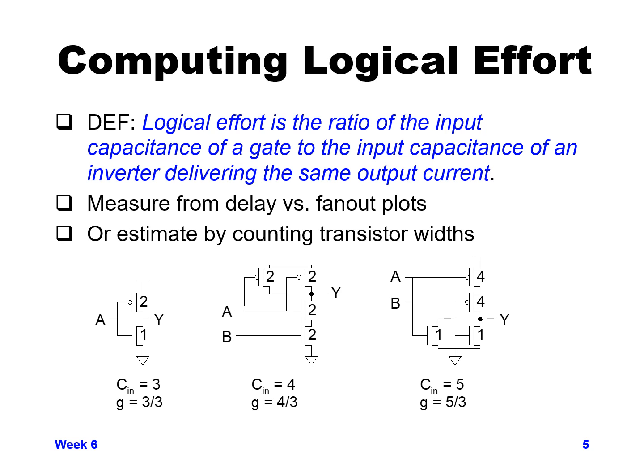So when we compute the logical effort for a 2-input NAND gate, each input goes to a size 2 PMOS and a size 2 NMOS. So 2 plus 2 is 4. So our Cin is 4. To normalize it to the inverter, you take the 4 divided by the 3 value, which is our normalized inverter, and you get G equals 4/3. So for a 2-input NAND gate, G equals 4/3.